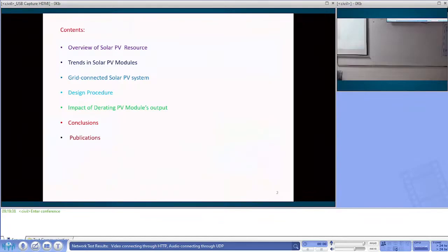That inverter will do three functions. DC to AC is one, and synchronizing with the grid, because all the developers of renewable energy plants have the responsibility to inject pure sine wave into the grid. So the grid-tied inverter, as it is called, will have DC to AC, synchronizing, and MPPT, three functions. About MPPT also we will discuss as time permits. Sir has already touched upon MPPT.